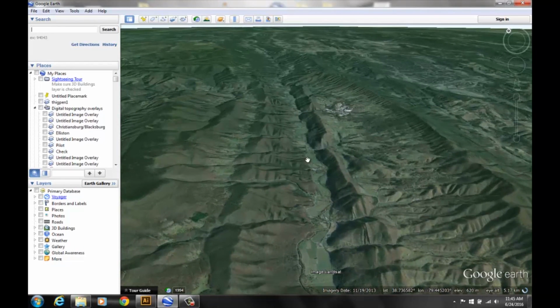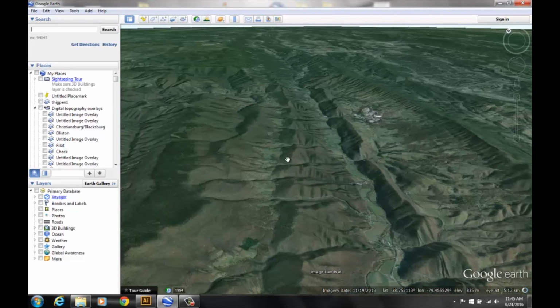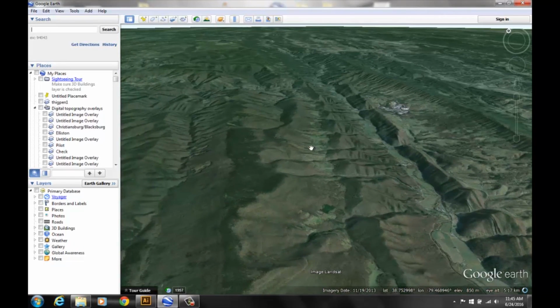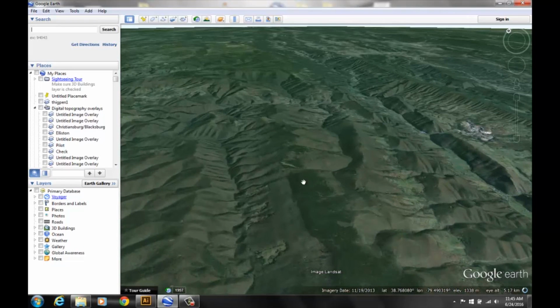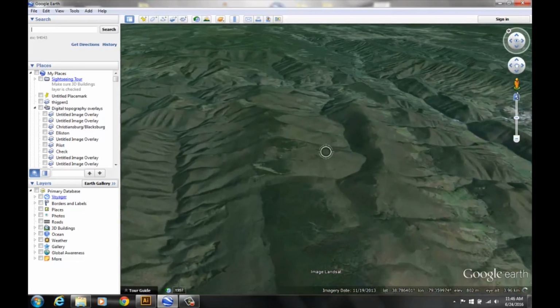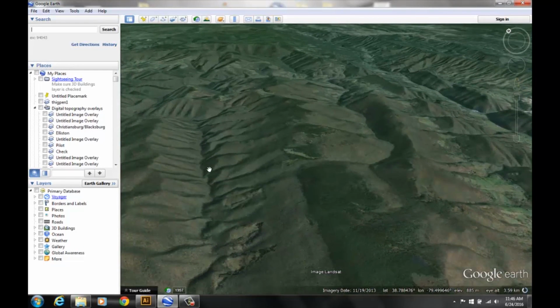And if you actually look at the grain of the topography, you can see that those very steep dips continue across the valley until you reach these flatiron type of features. Here, the strata are dipping off to the northwest. That dip decreases to the top of the plateau here where the layers are almost flat-lying, but then they dip back down to the northwest yet again. And if we zoom in on this valley, we can see more flatirons suggesting that northwest dip.